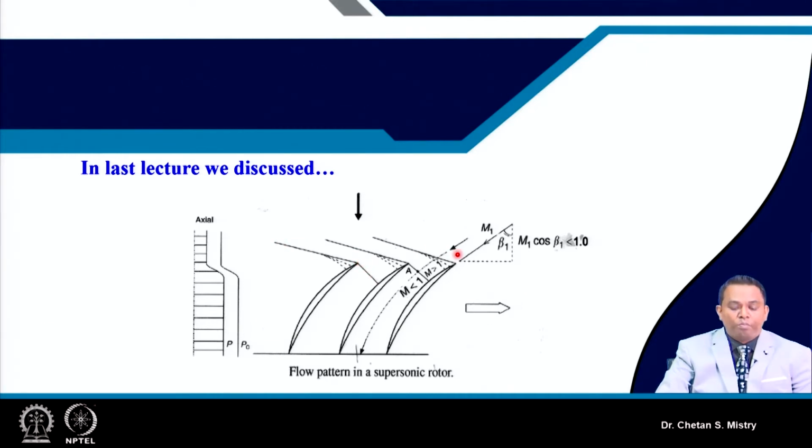Now because of the curvature of my suction surface and the inclination with the oblique shock, it will generate curvature, which we define as expansion fans. This curve moves away from the surface, and that is the reason why expansion fans are formed. Now when it moves downside, as we have discussed, the oblique shock will be striking on the suction surface of the next coming blade.